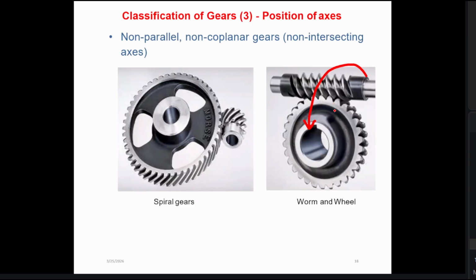That is why these worm and wheel are mainly used in winder motors. Hope you all have seen in automobiles that whenever we cut the power, the wheel will not be rotated, even though it is loaded, right? Even though our wheel is loaded, it can handle some amount of torque by limiting the worm to rotate, right?